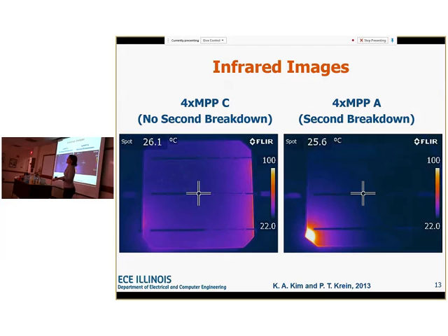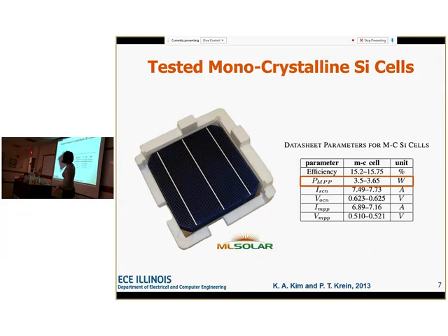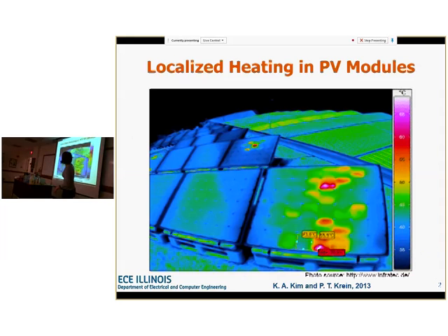It could be, but the literature I've seen all says that they tend to form in the corners and on the edges. If you go back to this, you can actually see on the edges that these are forming. That's usually where the silicon defects happen, when you saw that cell and cut off the edges. If you have any defects, it's usually there.